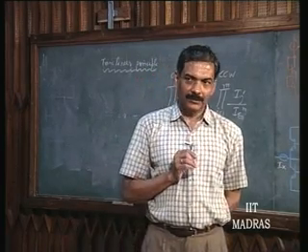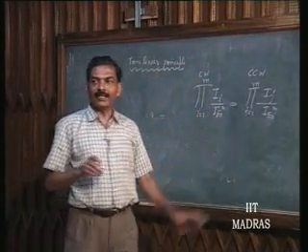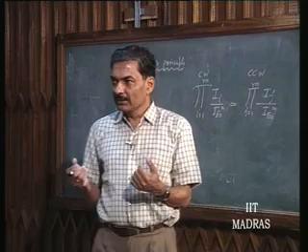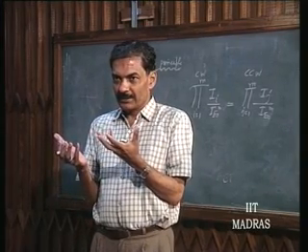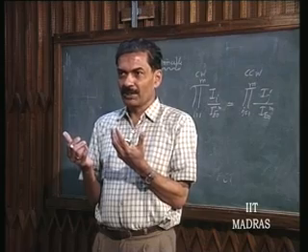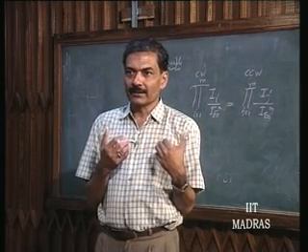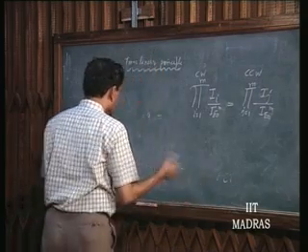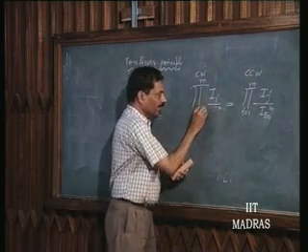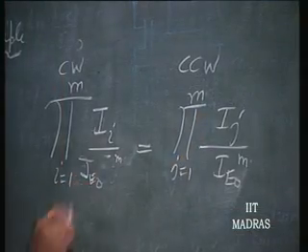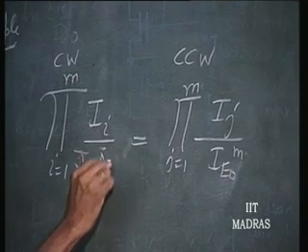Well, let us see a minor variation. Here, what is IE naught in terms of current density? JE naught. JE naught is the basic parameter of the IC. Okay, current density, because current density into area is what gives the current. So, I can split IE naught as JE naught times Ai.